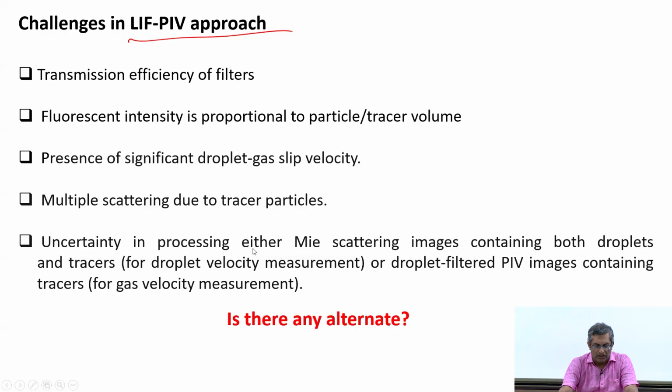So then the question is, if LIF PIV images have these challenges, obviously these challenges are amplified if your volume fraction or mass loading of the particle phase goes up. If you have more particles, then you have more challenges, especially when you have a scenario where you have two-way coupling between the two phases.